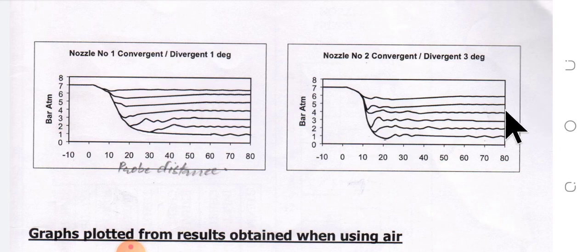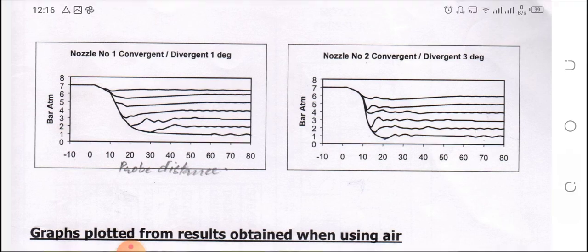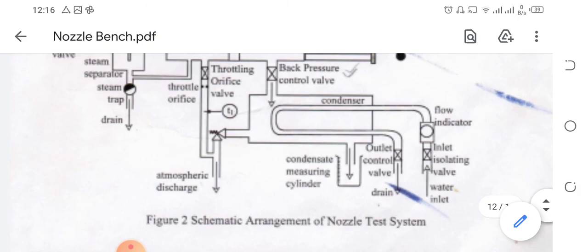As we are decreasing the pressure, this shock wave moves till the exit of the nozzle. This is the position along the nozzle basically. At 0 we have the throat, and after this point we have the divergent section. So you can see that for the series of pressure drops, we get to the design position. You can also find out at which pressure it will work as per design condition, or most efficiently, by a simple derivation that you already did in your workbook.